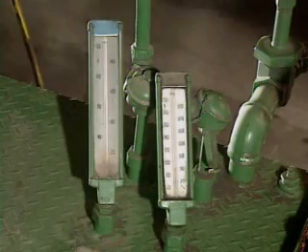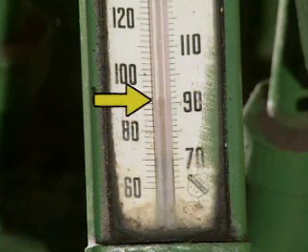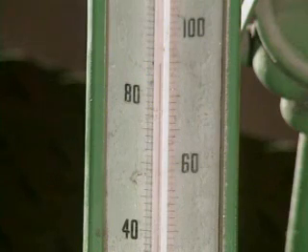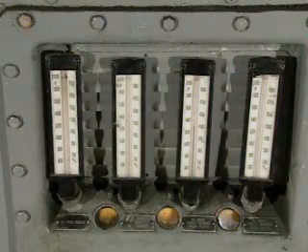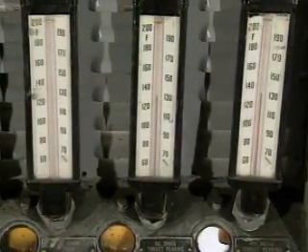It's also important to check bearing oil temperatures. This should be done at several locations around the turbine. Readings should be taken at the inlet and the outlet of the cooler to make sure that the cooler is operating properly. Oil temperature readings should also be taken at the supply and return lines. Oil temperature from the cooler to the bearing should be virtually constant. The temperature of return oil will vary depending on load, ambient temperature, and the specific bearing. While some variation in oil temperature is normal, a rapid change can signal trouble.